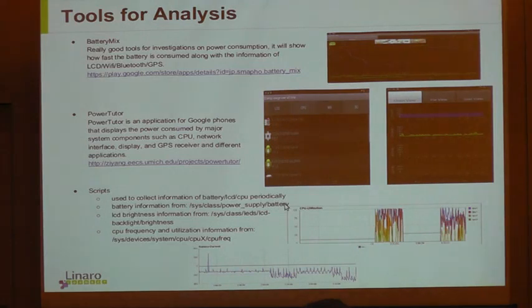Yeah. So it's always important to do real power measurements as well, if you can, because you're using software to infer how much power software is consuming. So you can have a feedback effect, or it may just not be very accurate, or maybe the granularity is kind of large and you miss things in between. So if possible, being able to actually hook it up to a battery simulator or even a bench power supply that gives you current measurement would also be useful. The problem there is we don't have the right hardware. That's very difficult, I understand.